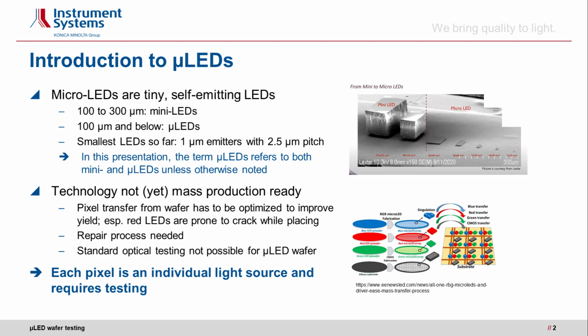And what concerns Instrument Systems is the standard optical testing, which is not really possible for micro-LED wafers. And we have to keep in mind that each pixel of such a micro-LED wafer is still an individual light source with individual properties and therefore requires individual testing.